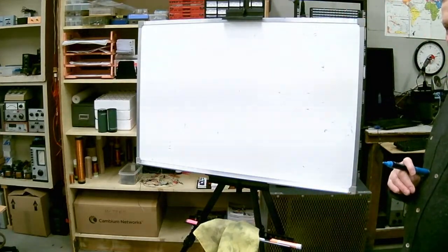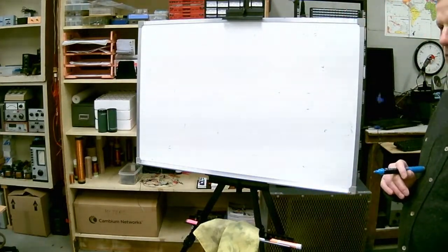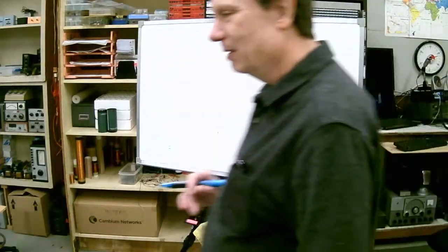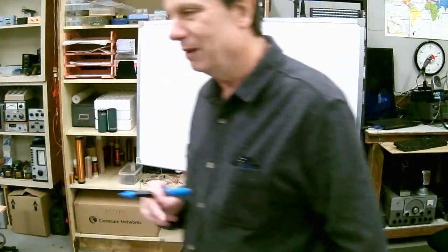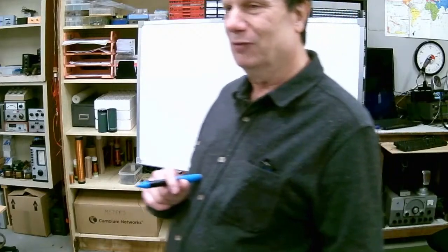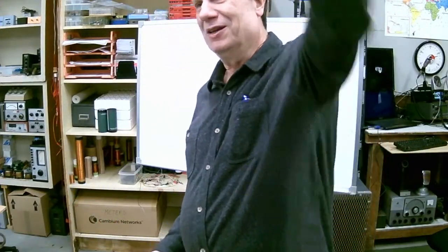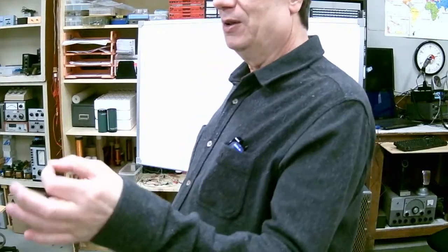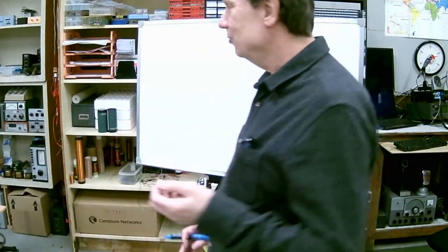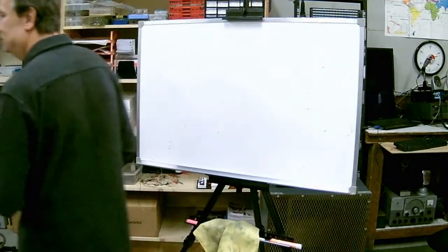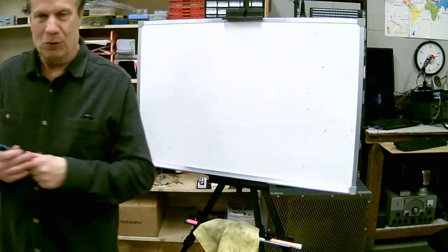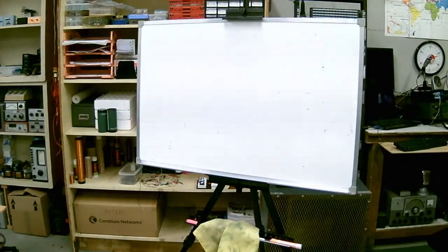So we usually measure antenna field intensity in either microvolts per meter or millivolts per meter. It's the voltage that we induce across a 1 meter long antenna, which we can then use for measuring the actual signal, depending on how strong a signal we're dealing with to start with.